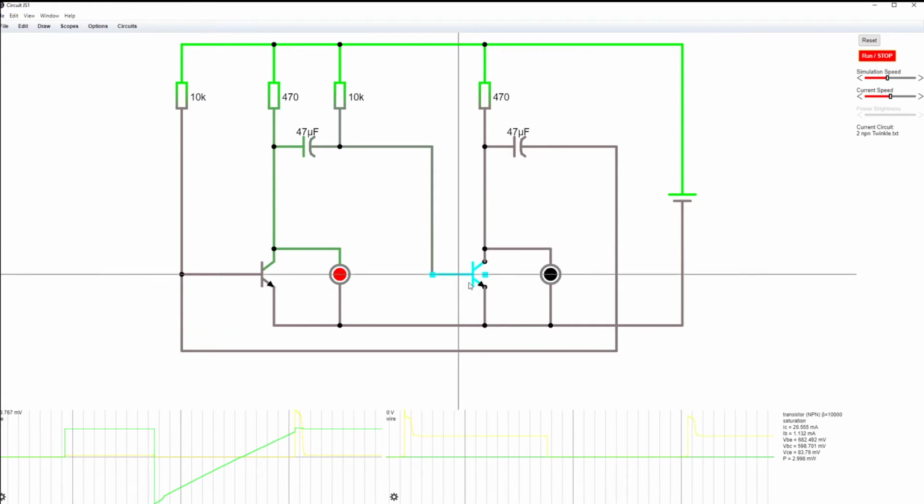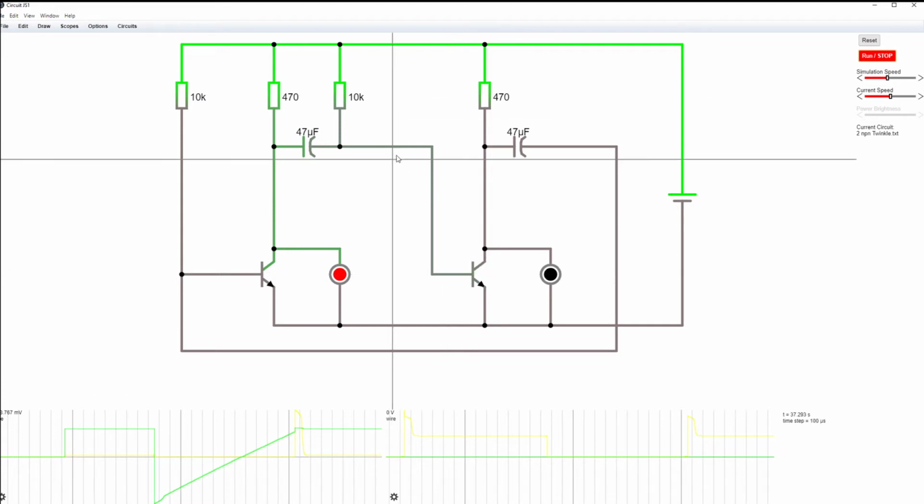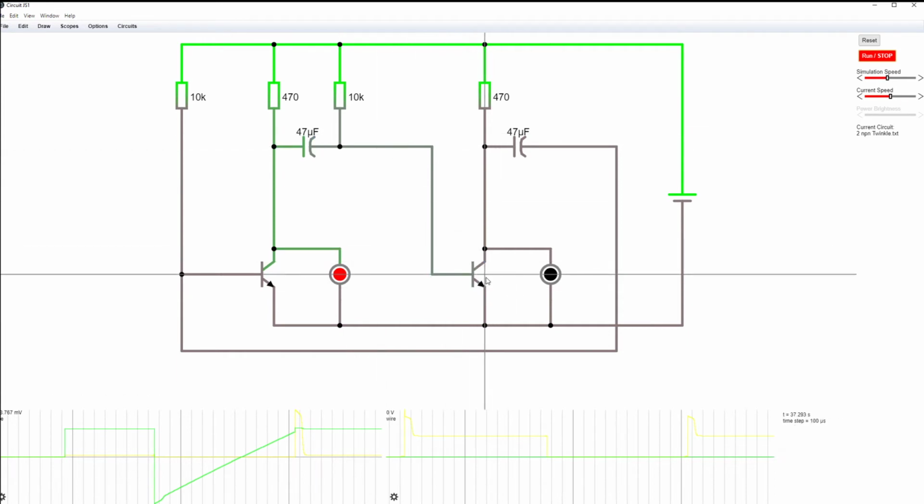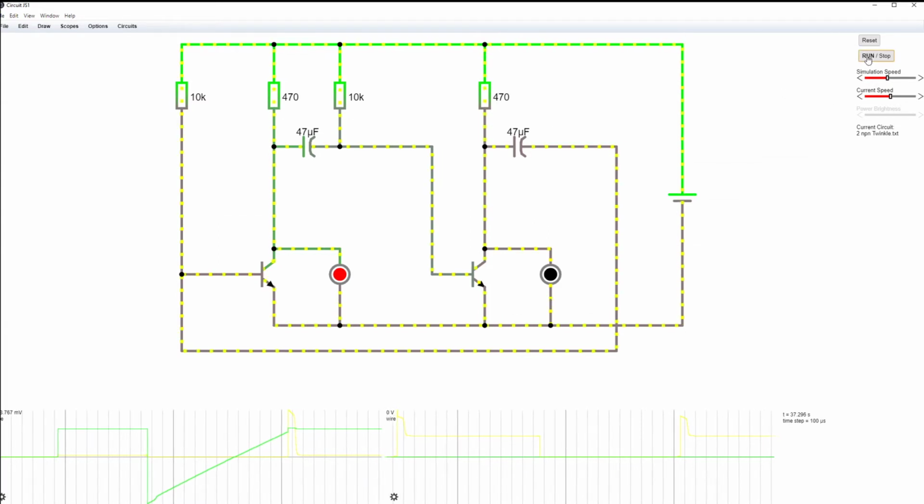We already said that this transistor acts as some sort of gate. How it works is, this over here is the sensor. When the sensor hits a certain voltage, it's going to allow current or electrons to flow through the main terminal of it. The switching point is at about 0.7 volts. So we can see over here, as the capacitor gets to 0.7 volts, it's going to turn on this transistor to allow current to flow through it. So let's watch it again.